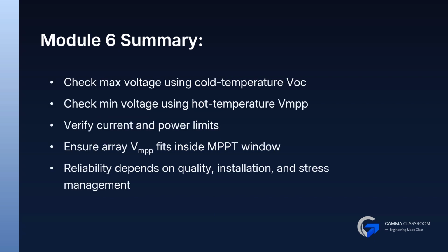To summarize, check maximum voltage using cold temperature open circuit voltage. Check minimum voltage using hot temperature maximum power point voltage. Verify current and power limits.